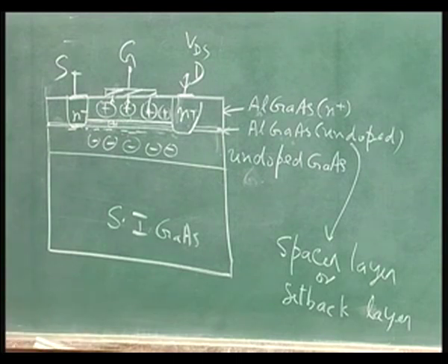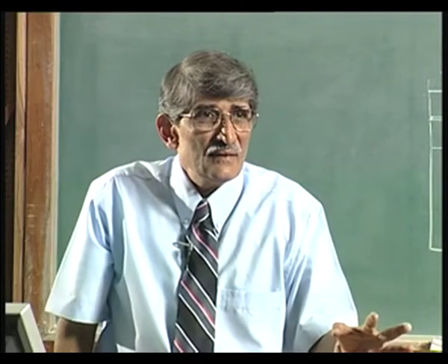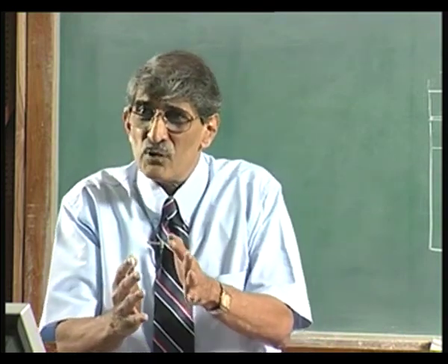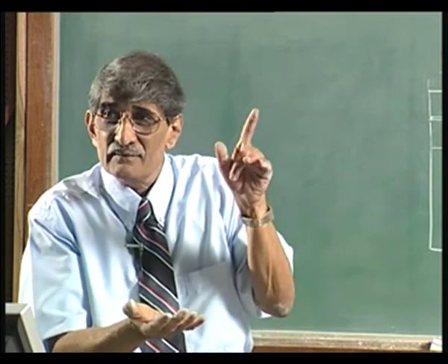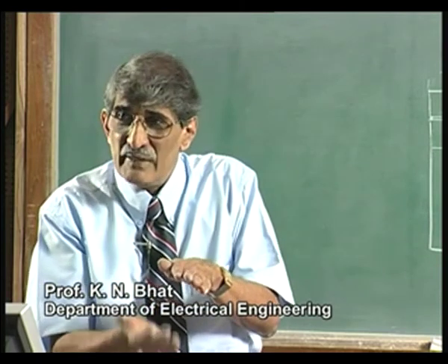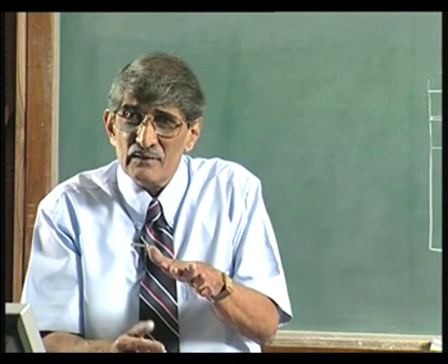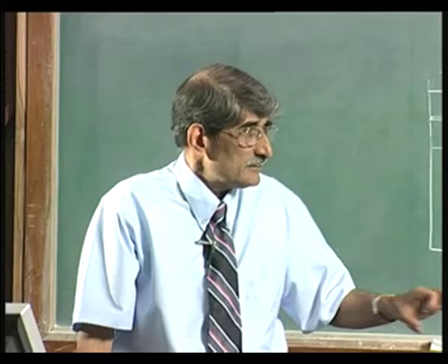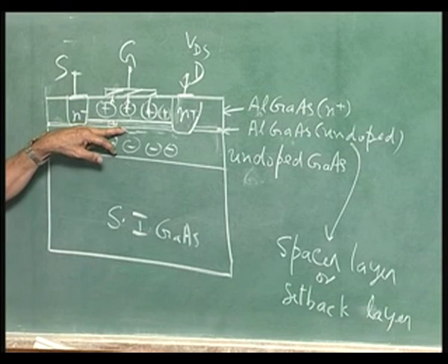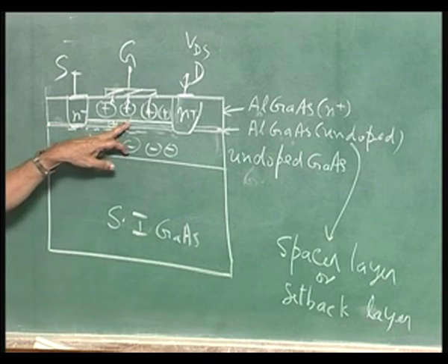Okay. So, let us go into the analysis further. What is the situation now? If that point is clear, that is there are field lines, fully depleted layer is there, but most of the depletion layer is interacting with the gate, Schottky barrier, part of that is interacting with the p-n junction, field in the opposite direction. Now, ultimately you must reduce the field in this direction. If I reduce the field in this direction, what happens? This collapses, and what happens to that boundary?